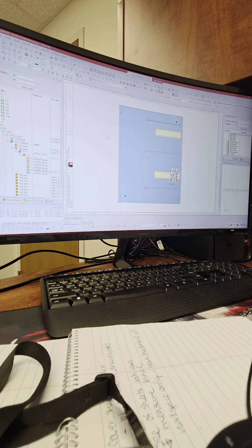But let's just say you grab it from the library. Let's drag and drop it into the MP folder. If you scroll up a little bit, make sure, yeah, that one right there. It looks like it's under the E folder. Yeah, E1, that's the one that we just planted. You can grab it by the E1, you don't have to grab it by the model, just to drag and drop the part. And there's your ground bar that you need to place under your VFD.